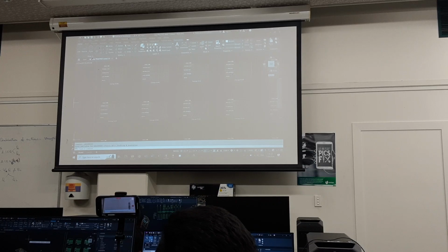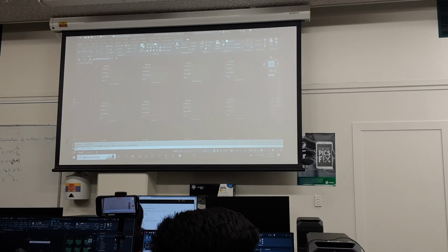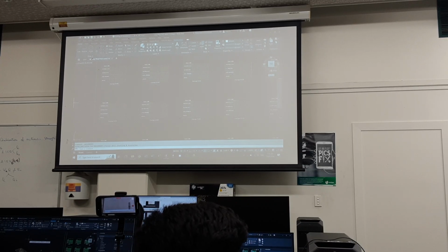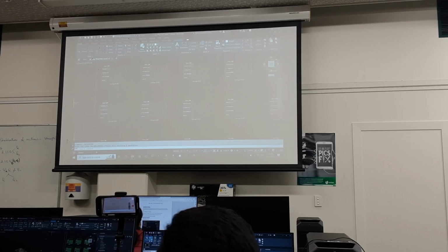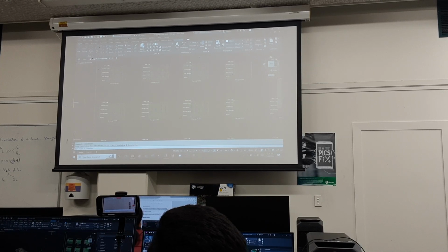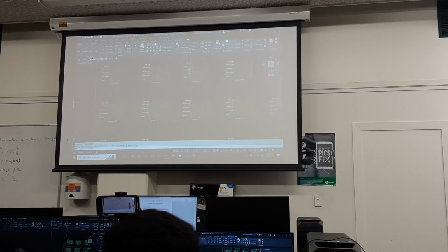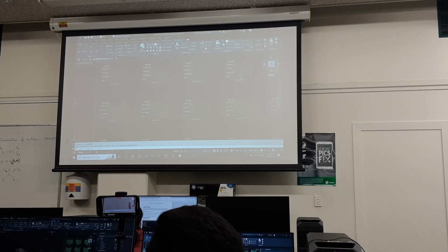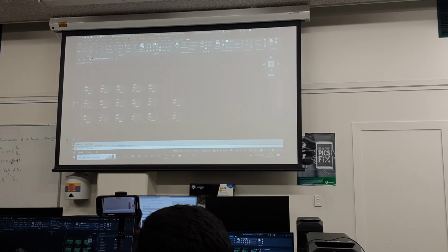Maybe that's how you want to do it, or maybe you want to do it in AutoCAD and adjust them multiply there using match property, the paintbrush. It's up to you. I'm just giving you that option before you export it, or you can do it afterwards. It depends on how easy you're finding Civil 3D or how hard you're finding it.